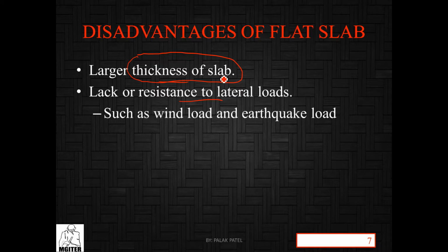Imagine there is no beam, so the load will be transferred from slab to column directly. That requires more reinforcement, because transferring the load is not easy.